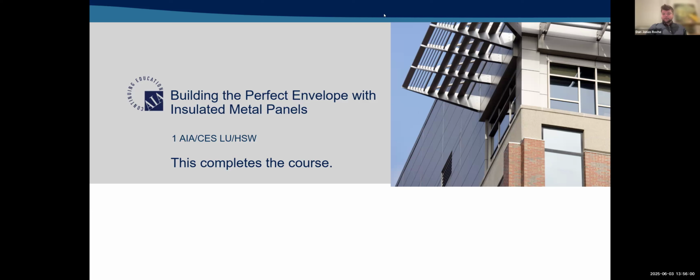A question from Matthew. What are some negatives of the IMP system? Negatives. I don't think about the negatives, but one thing I would say is that an insulated panel isn't for every building wall, every application. If you have a building that has a lot of openings, then maybe an insulated panel isn't quite the right application.